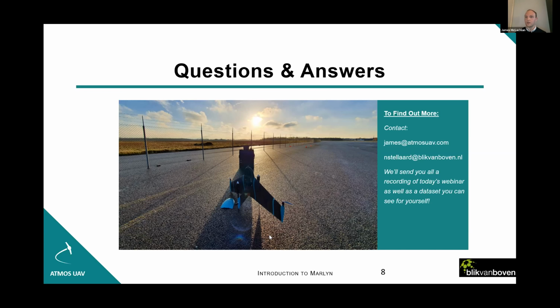Sorry, go. What I saw in GeoTagger is that you can handle a lot of various types of data. Well, we use an MNet, for example, like you mentioned, but there are several types of units you can handle there. As far as I understood, you need to have RINEX data. But it's possible to convert. So you have a .t05 file that you get from a Trimble base station, and then Trimble has a free to download software that you can use to convert .t05 to RINEX, and then it's possible to put into GeoTagger.